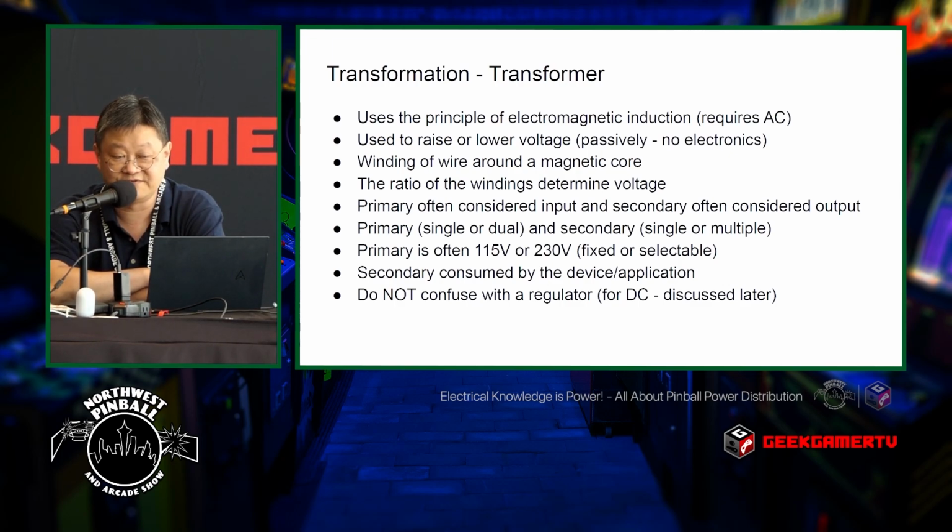If you put in 115 volts, but it's set for 100, you are putting in a ratio of 1.15 over what's expected. So if the output is 50 volts, your output will be 50 times 1.15. I don't know what that number is, but you can run it through a calculator. That's the bottom line here.